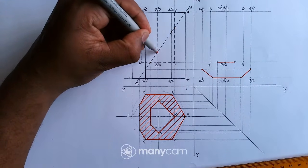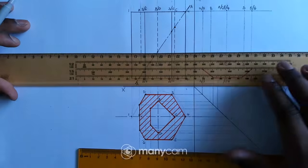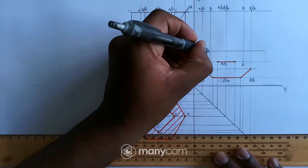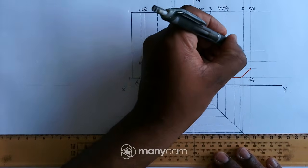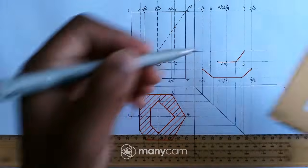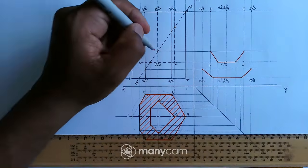Now I'm moving to the next point. Here the cutting plane is cutting 2 lines, line BB and DD. So I'll have to project this point to those 2 lines. Line BB is there, that means I'll have a point there, and DD is there, that means I'll have a point there. Then I connect those points from here to there, and also this side, connect those 2 points. So I'm done with this point.